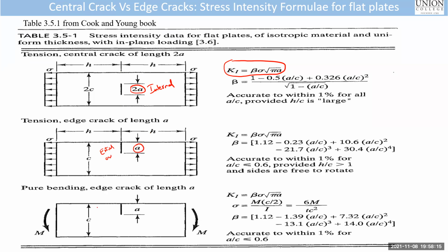And again, this is a surface crack or edge crack with length a. All of them have rectangular cross section, and the difference is not just where the crack is present, but also the loading. You have a tensile loading here, which is the most dangerous type of loading, right? We're talking about K1, that's why it's for that mode, the opening mode. You have stress intensity occurring at that internal crack. That's K1 equals beta sigma root pi a.